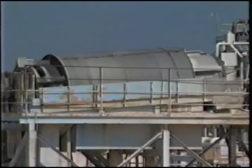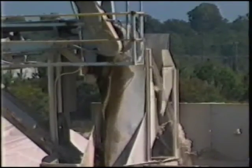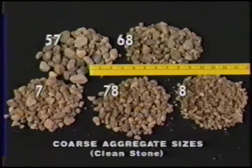Here, water pressure and the turning action of the screen are used to separate the sand and gravel. Oversized gravel is taken to a crusher just as in a stone plant for primary crushing. Gravel products are sized over a screen deck and are conveyed to separate stockpiles. The most common sizes are number 57, number 68, number 7, number 78, and number 8 gravel.